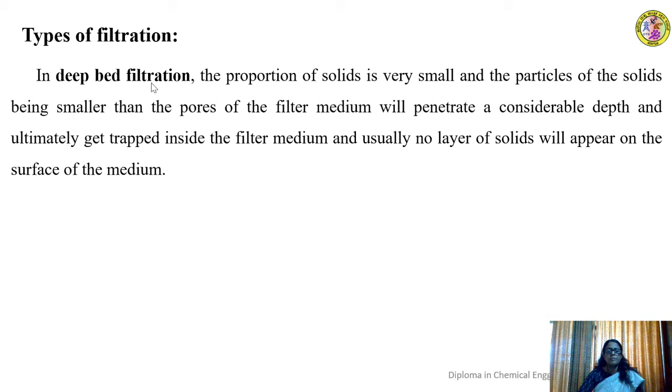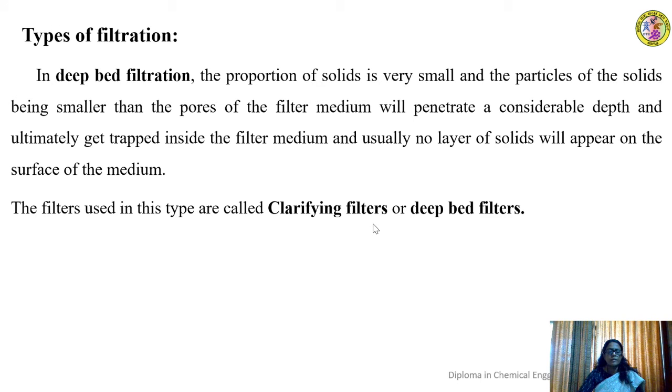Okay, so let us understand deep bed filtration now. It is the filtration in which the proportion of solids is very small, and the particles of solids, being smaller than the pores of the filter medium, will penetrate a considerable depth and ultimately get trapped inside the filter medium, and usually you will find no layer of solid on the surface of the filter medium. So that is the nature of deep bed filtration.